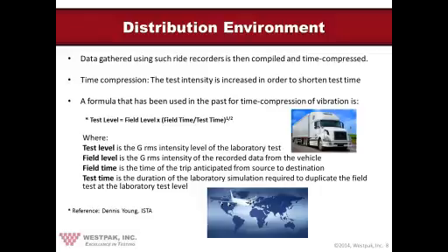Now, there is a limit as to how far someone can actually time compress a certain profile without breaking it down and destroying the product in the process. Let's take lasagna, for example. You can bake a lasagna at 200 degrees for 3 hours, or 300 degrees for 2 hours, or even maybe 350 degrees for an hour. But you certainly can't bake it at 1,000 degrees F for 5 minutes without just burning it. So the same kind of ideology applies here when we're time compressing vibration that's recorded. One of these time compression formulas used by the industry is shown on this slide. Typically, you wouldn't want to accelerate anything more than 3 times what you actually measure.